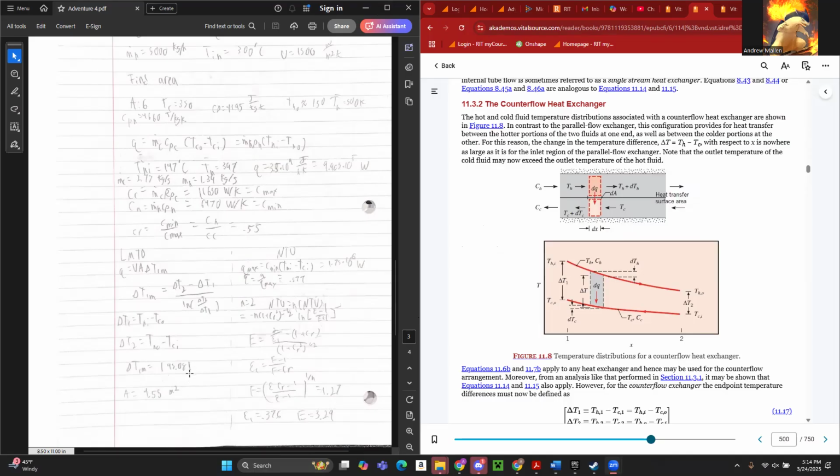However, as I mentioned, because this is a more complicated heat exchanger, using the efficiency NTU method is far better in this instance. So since we have the CH and the CR, the first thing you do in cases like this is you want to find the Q max.